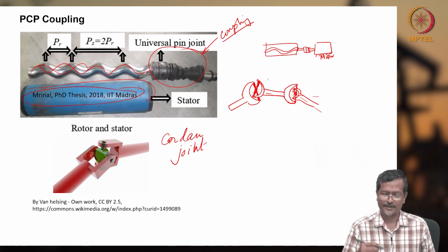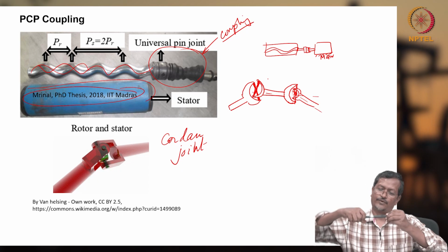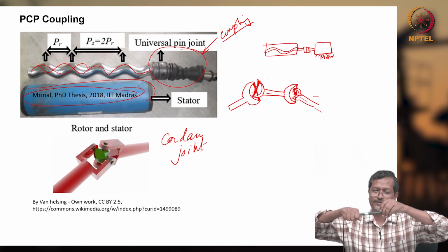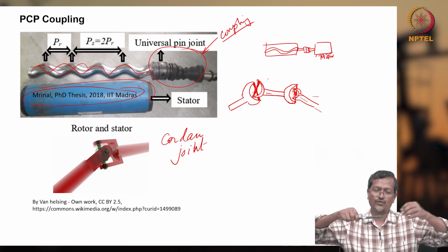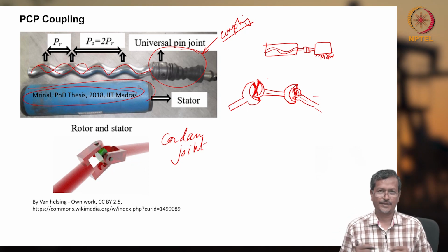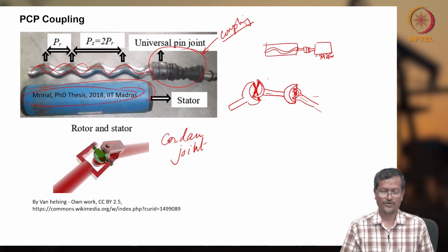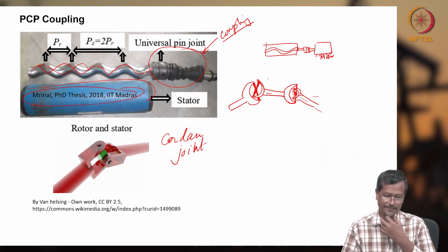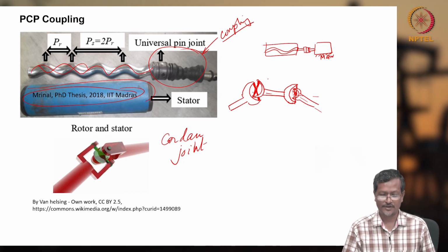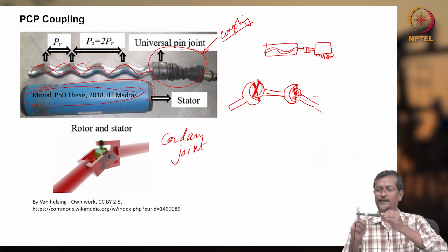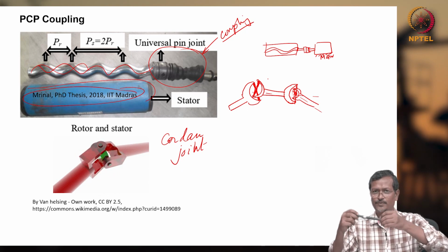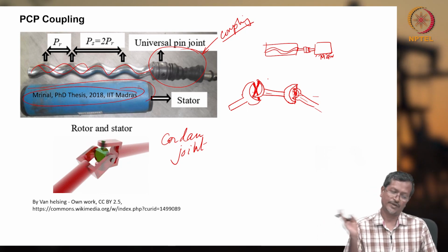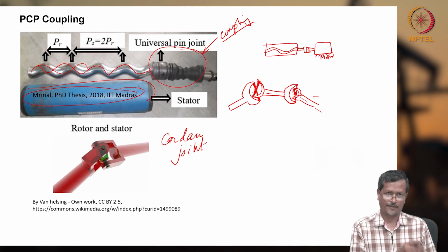So, this way you can give flexibility to the shaft, so that one end is fixed, another is moving, although rotating and giving sliding motion also. Then this will not create extra force on your rotor. So, ESPCP and other PCPs use this sort of joint, otherwise it will fail. There are also some gear-type mechanisms, but this is the most commonly used, called a universal joint. One end there will be a pin, another will be a pin when you are rotating, so it will move smoothly, and there will be no extra force coming into your motor or going into your PCP.